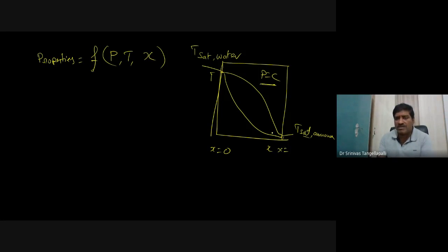of ammonia. So as per our requirement, for example, we are designing a Kalina cycle. As per our design, for example, I want a particular temperature exactly between the saturation temperature of water and the saturation temperature of ammonia. Accordingly, we can control the concentration. As per the concentration, we can control the saturation temperature of the mixture from the bubble point temperature to the dew point temperature. So finally, the concentration plays an important role in deciding the performance of the Kalina cycle.